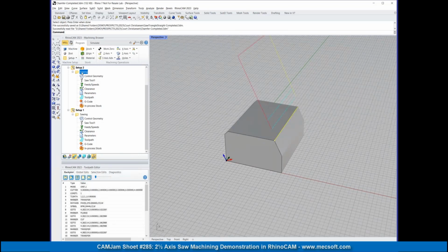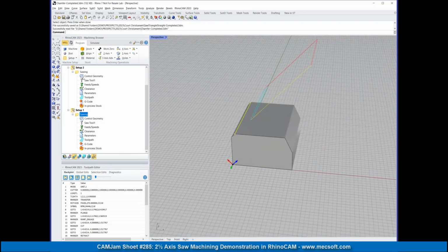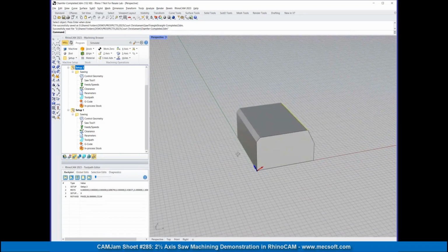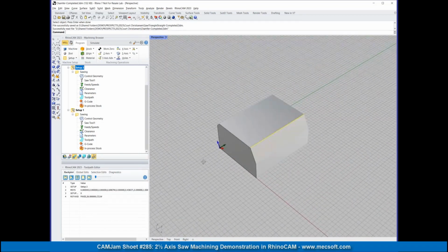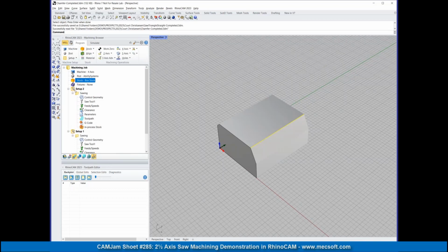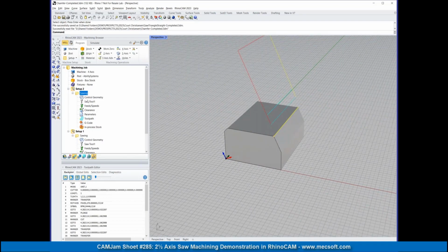So I've created some toolpaths already. So we got two chamfers at different angles. And then again, the important thing here is, how do we set up the orientation? Yeah. So let me show this to you so we can do it, and then I'll go back and actually show you how it's done. So I picked that edge, and then I created a toolpath. Let me run it.